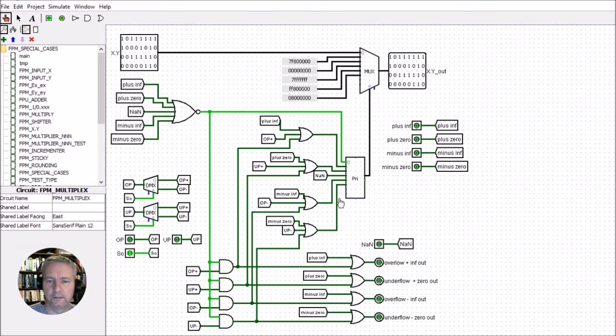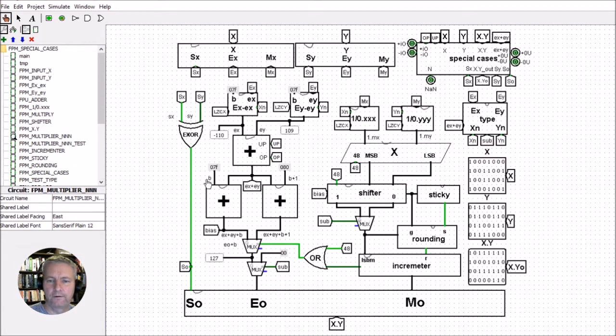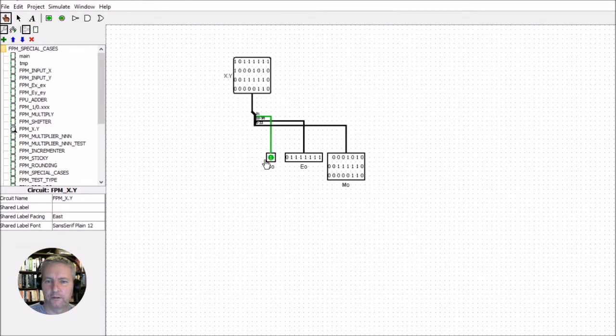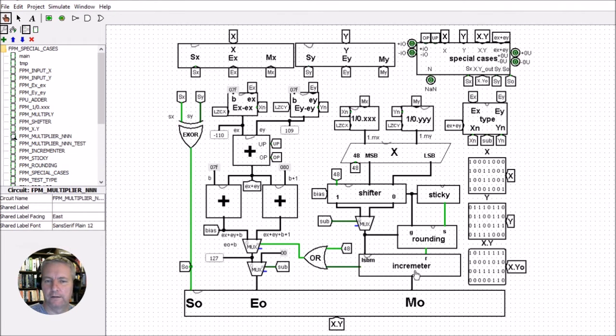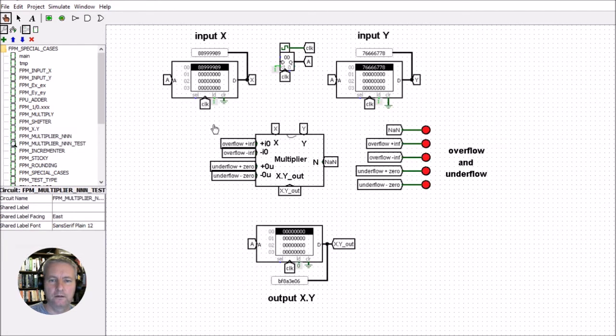And we choose these values depending on our little circuit here. Now I don't want to go through all the details of this circuit, but it will be in the course, and I'll go over every bit of it in minute detail. If I head up to the top section again, we've covered everything we have in here. Within this unit we just have a concatenation, so we just join the three values together to get that output. There's nothing else in there we want to talk about. The exclusive OR is quite straightforward. To get the sign, you exclusive OR the sign of x and the sign of y, and it gives us that final output.